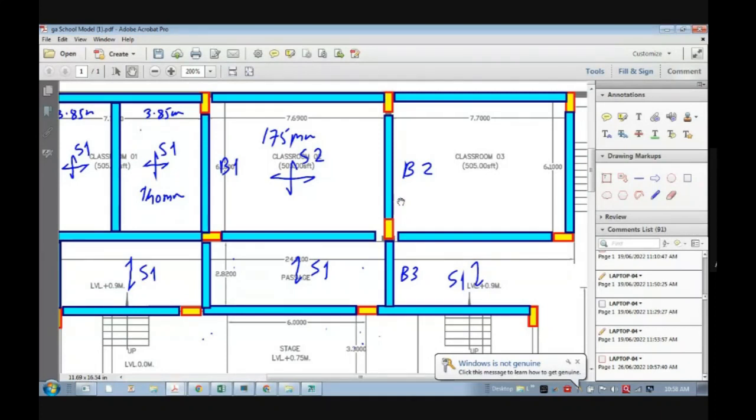Generally horizontal, see, this is my opinion and suggestion, you can verify whatever we are discussing in the model. But I feel this is a better choice because whenever any beam is resting on the column, generally the spans are large, and it is single, due to that there will be moment along the deeper axis of the column. But here the bending moments generated will be on the weaker axis of the column.